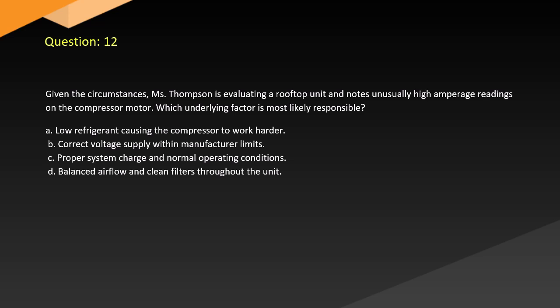Question 12. Given the circumstances, Thompson is evaluating a rooftop unit and notes unusually high amperage readings on the compressor motor. Which underlying factor is most likely responsible? A. Low refrigerant causing the compressor to work harder. B. Correct voltage supply within manufacturer limits.